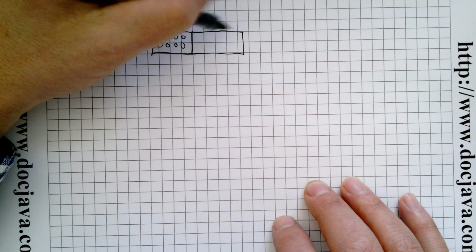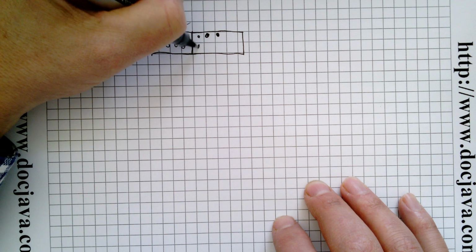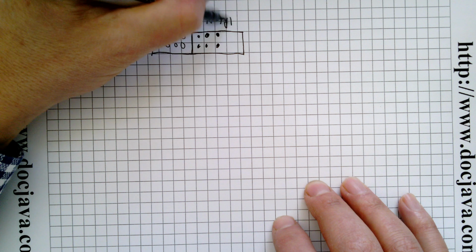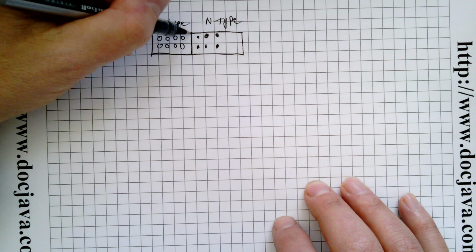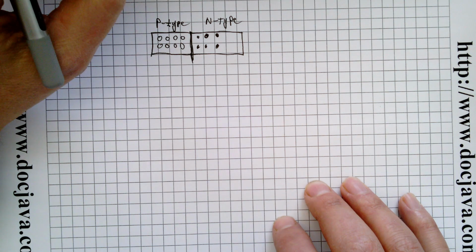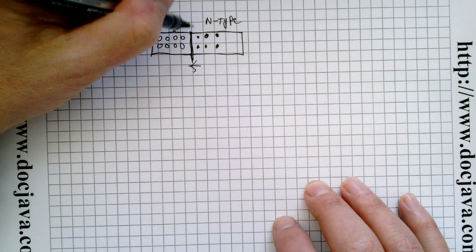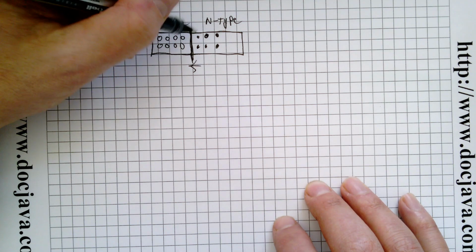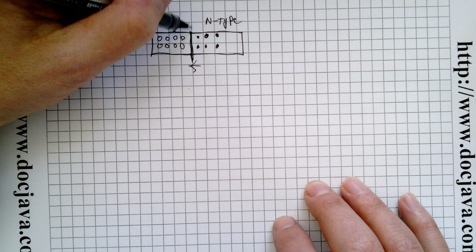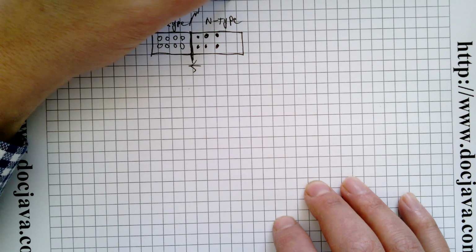Then there's something called the electron doped material, or what's known as the n-type material, and it's put right next to the p-type material. And what you get in here is electron migration, combining with the holes. And when the electron combines with the hole, it falls to a lower energy level, and it emits a photon. And this is called electroluminescence.